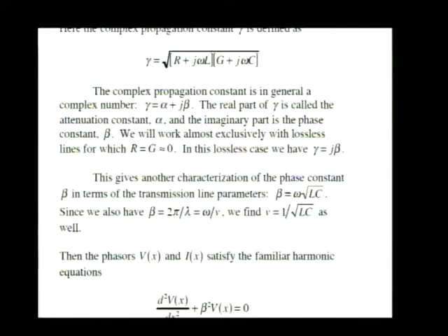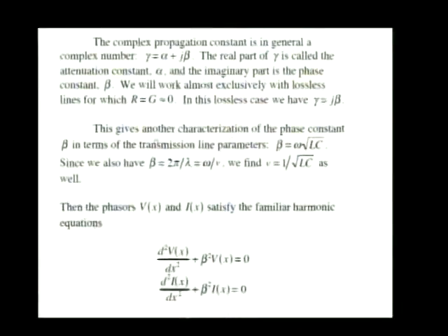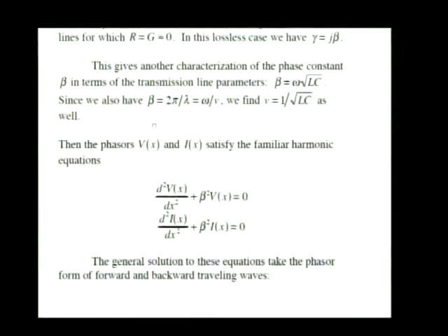And generalizing the results we have here for lossy transmission lines is not too awful difficult. You'll find those results in many textbooks. You can refer to them if you'd like. And thirdly, the software. Well, software can deal with the general lossy case just as easily as the lossless case. So let's let the computer do the dirty work and start our design by considering lossless lines. Use that as a starting point for our computer design, and let the computer compute the differences between our pencil and paper lossless study and what the real world lossy line would give us.